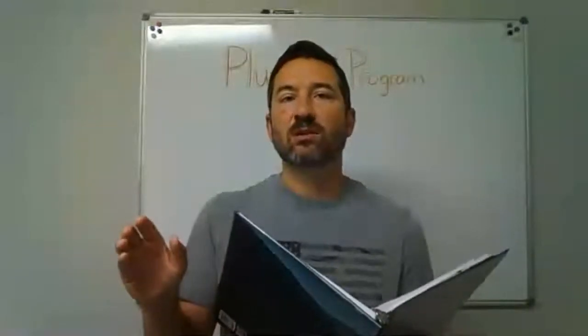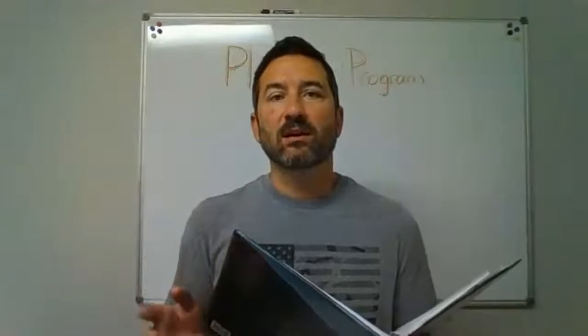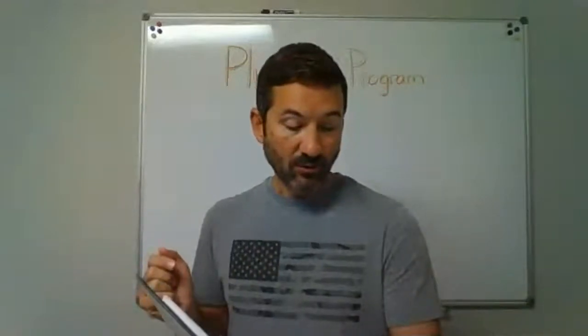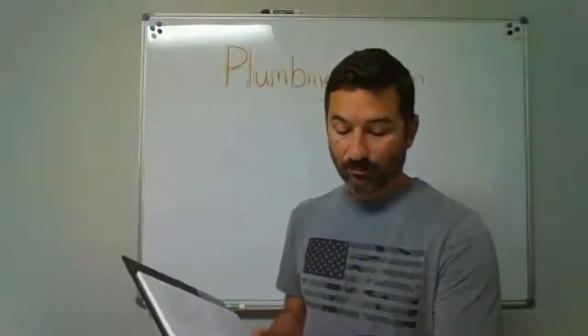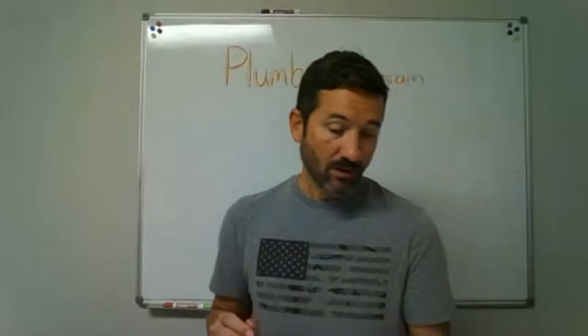And then you say, well, how far away can the vent be from that trap? That's going to be basically 4 times the pipe size in feet. Now, they give you a little table, 909.1. There it is, and they'll give you all the numbers right there. But basically, if you take the size of the trap and multiply that number by 4, it will give you the distance from the trap in feet, that maximum. Okay, that's where we left off.